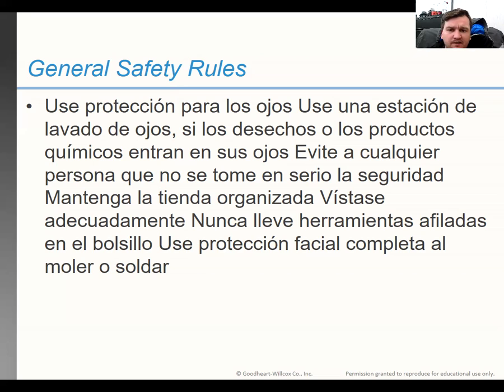Keep the shop organized, always. Dress appropriately. So you want shoes, closed-toed shoes. You don't want to be wearing flip-flops or something like that. Take jewelry off, necklaces, things like that. You want to put them away and store them somewhere else. Never carry sharp tools in your pocket. Those can stab you. You can damage people's vehicles as well. If you have it in your back pocket, a screwdriver or something, sit down in someone's car, you can tear their upholstery.